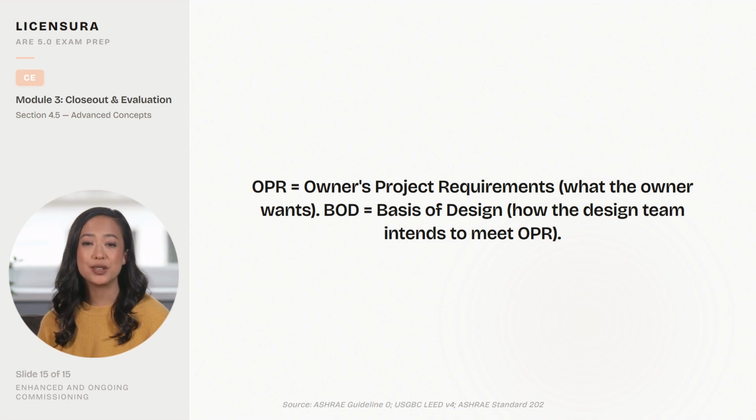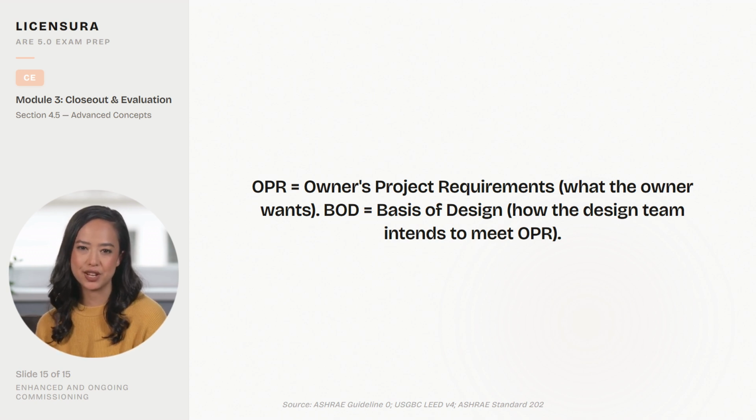OPR equals owner's project requirements, what the owner wants. BOD equals basis of design, how the design team intends to meet OPR. The CXA verifies that the BOD addresses the OPR and that construction meets the BOD.